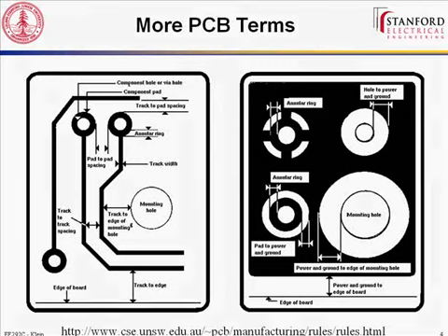And moreover, is it not the case that if you want to route ground, there is voltage drop, and to avoid that or to keep that to a minimum, we use large areas of copper? That's correct. So there is a voltage drop across every trace that you have current flowing through. And so the thicker your traces, or at the extreme having an entire plane layer, will help reduce that voltage drop because it reduces the resistance. So it's a good thing to make your traces as wide as possible, or to use plane layers for these high power traces.